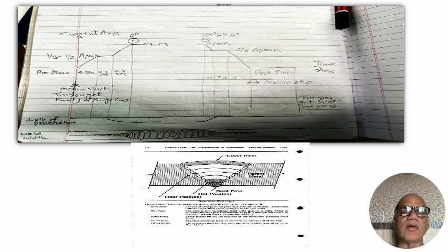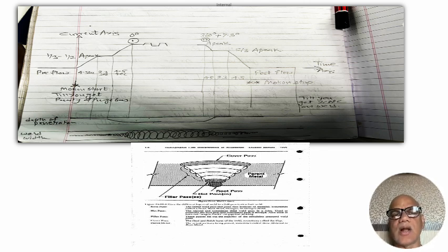At this point, when this 2-3 seconds of 2/3 current is stabilized and the craters are filled up, you will then stop your rotation or the movement between the torch and the job. The downslope starts further, comes to 0. This is the point where your post flow is going to start.